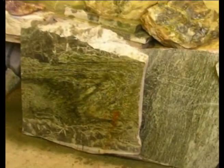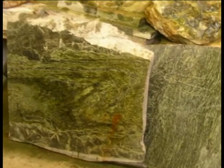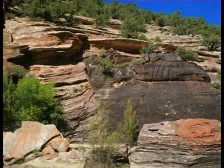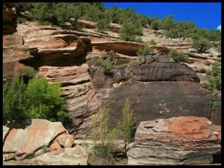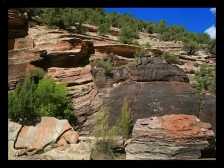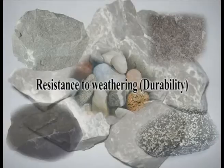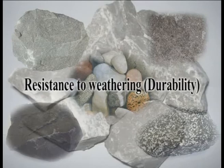Structurally speaking, such features as bedding planes, foliations, cleavages, joints and flow structures, which might not be fully represented in small sized test specimens but which may be present in rock masses on a large scale, have to be given consideration. Resistance to weathering, that is durability. It is essentially a geological character of a stone that is commonly determined by its composition, texture and structure on one hand, and the climatic environment where the stone is ultimately used on the other hand.